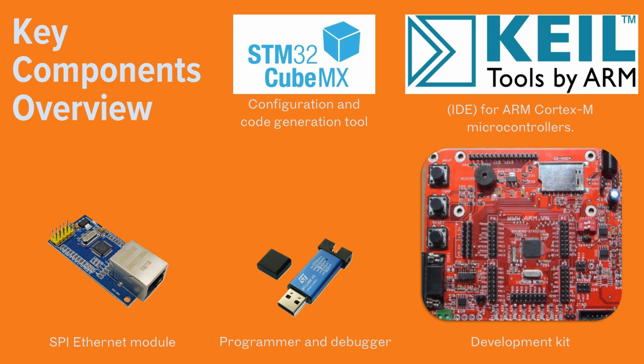For testing and verification, I will use Wireshark to capture and analyze BACnet IP packets at the network level, and YABE, Yet Another BACnet Explorer, to discover BACnet devices, browse objects, and test communication.